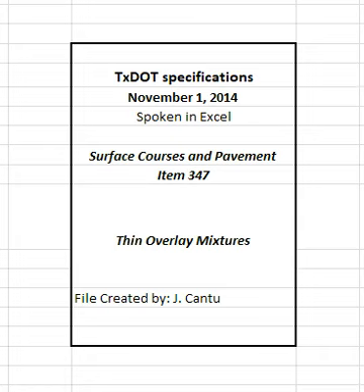4.7.3.1.2 Thermal imaging system. Review the output results when a thermal imaging system is used, and provide the automated report described in TxDOT 244F to the engineer daily unless otherwise directed. Modify the paving process as necessary to eliminate any recurring, moderate or severe, thermal segregation identified by the thermal imaging system. The engineer may suspend paving operations if the contractor cannot successfully modify the paving process to eliminate recurring severe thermal segregation. Density profiles are not required and not applicable when using a thermal imaging system.